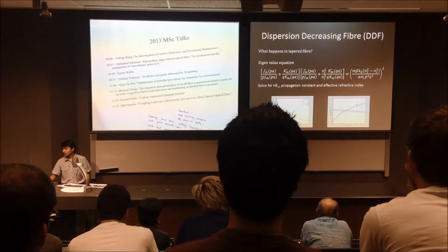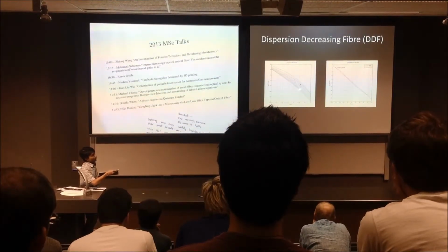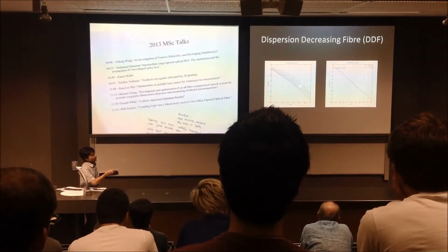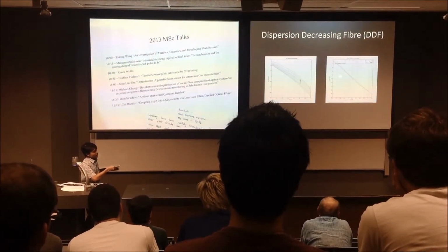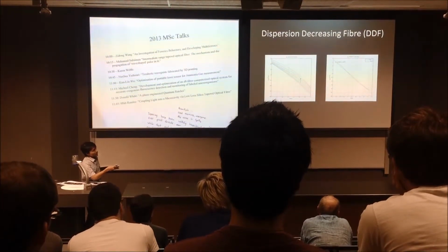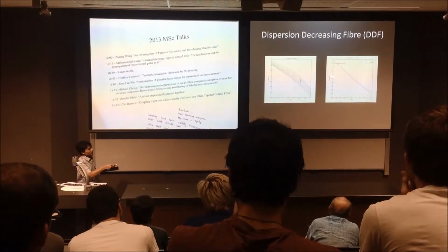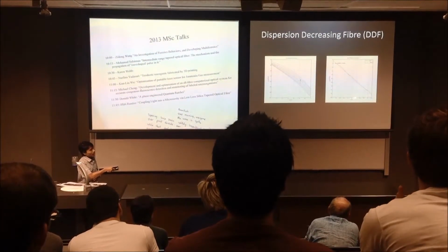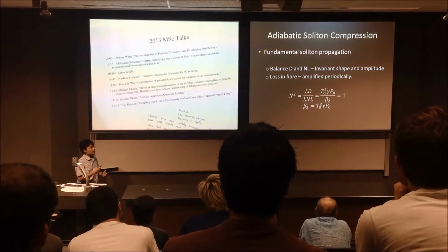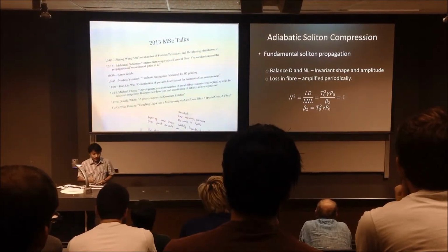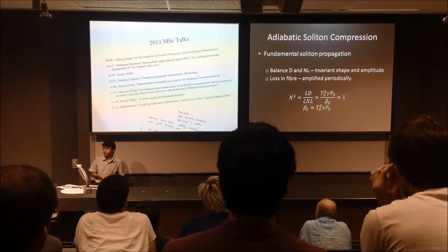By having this simulation, we can see that in the anomalous range of lambda, we will decrease the beta 2, and by having the beta 2 at 1550, we can see in this range of tapering, we almost have a linearly fit beta 2 function according to core radius. So with this well-defined beta 2, we can simulate how soliton propagates in a fiber.